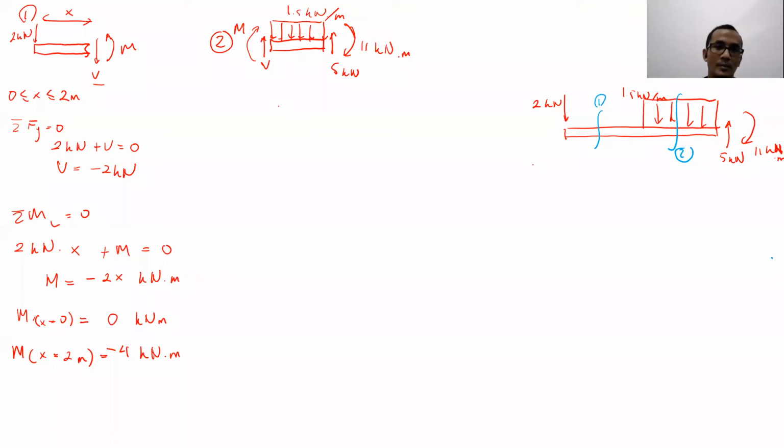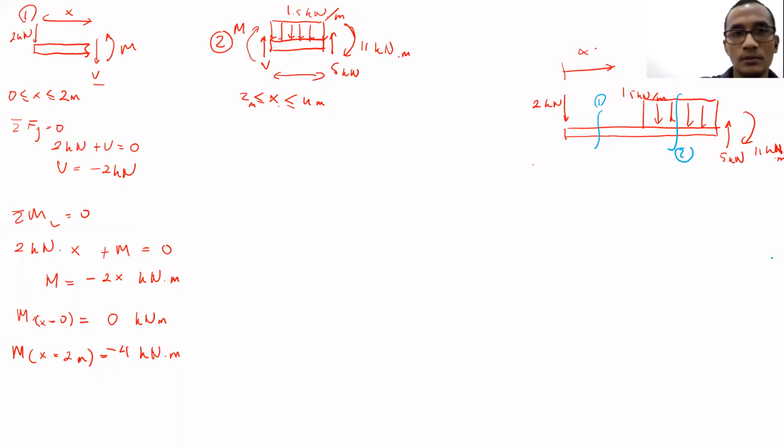So this is the free body diagram that you're supposed to solve, and it will walk from x equal to 2 meters to x equal to 4 meters, right? Yes, sir. And here, the distance from here to here is not x anymore, because x is from the left. Remember the x is from the left. So this one is not x anymore, but 4 meters minus x. Okay.